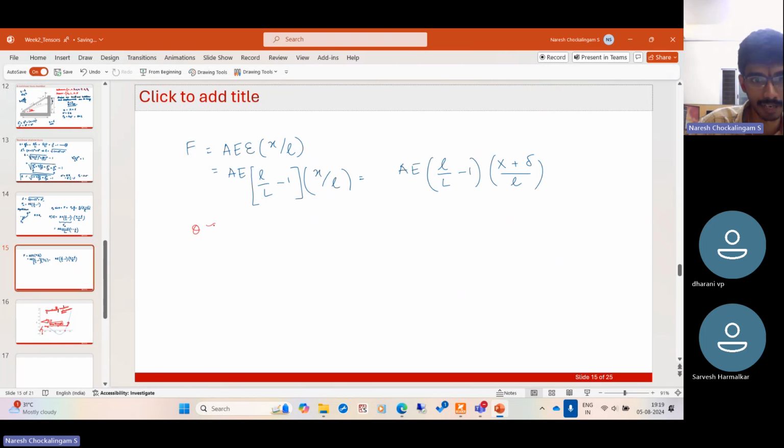So theta is approximately equal to theta naught. Make this approximation here. So this will become just theta naught, sine theta naught. And this is just a small strain. This will reduce to the small strain expression that you can solve, and you can get the initial stiffness as AE by L.